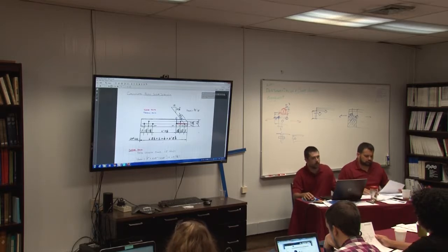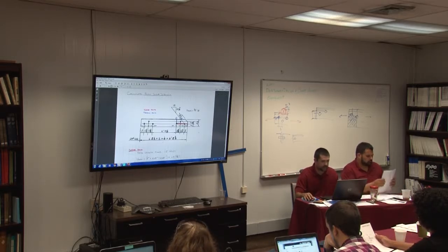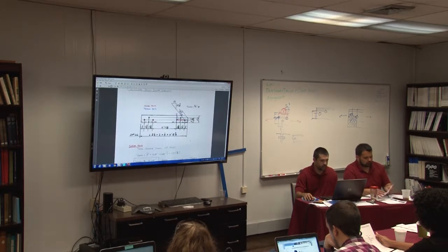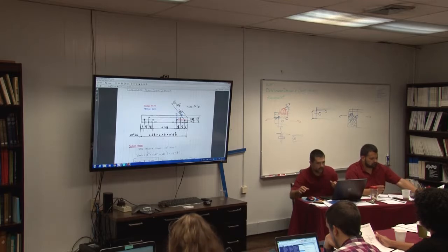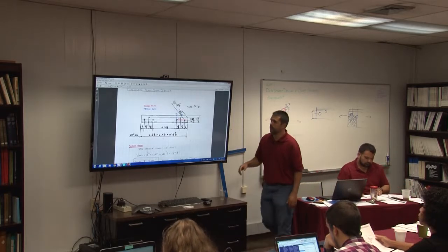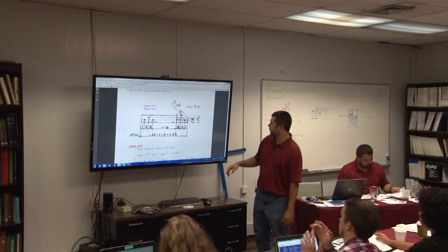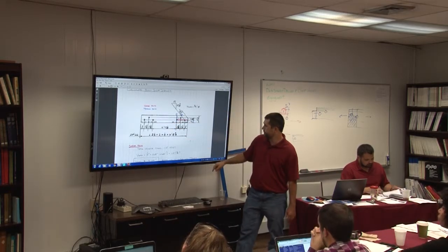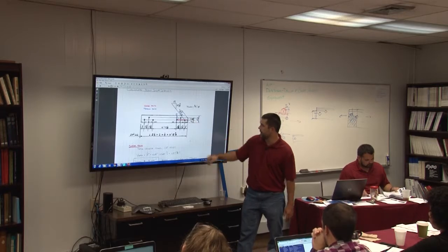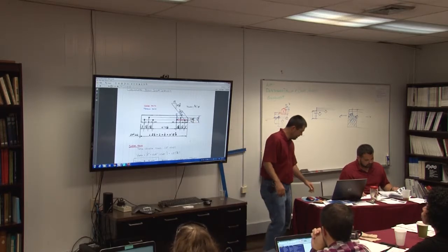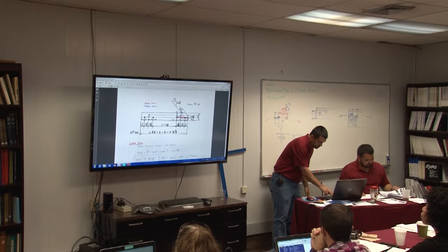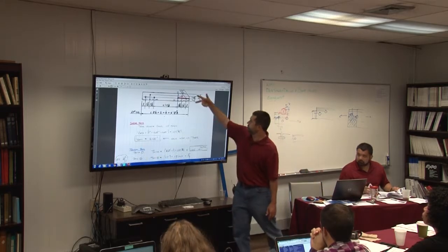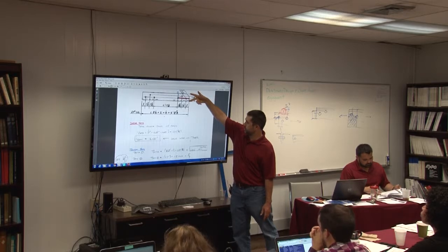So this actually comes from the DP tower. This is one of the diagonals on the DP tower, and the idea is, what do we put in as the shear path and tension path in our rupture check? I can see that my connections are symmetric, so I can look at either end. In general, it's a 2.5 by 2 by 1/4, but the 2.5 is in this direction.